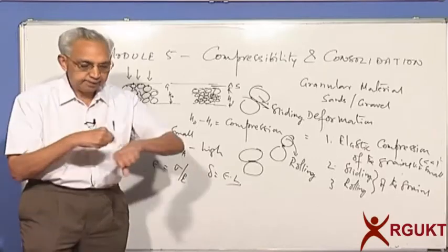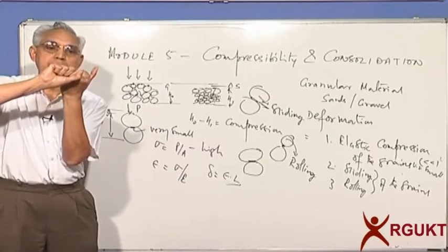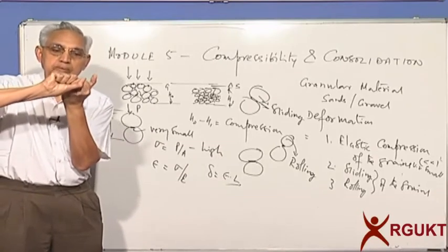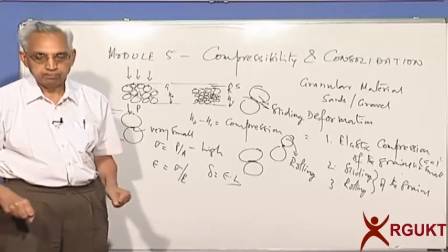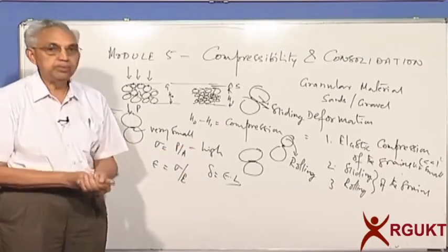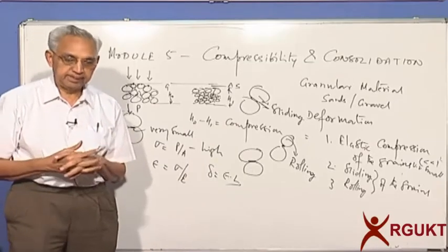So here is another example. I have one grain resting on it. When you apply the load, this grain may try to move, that is sliding, or it can rotate, which is rolling. So these are the three most common deformation mechanisms in case of sands.